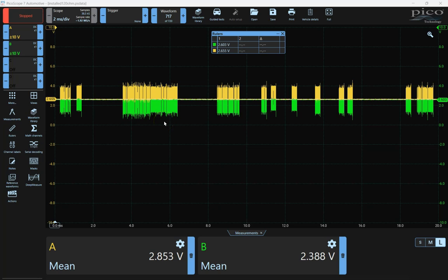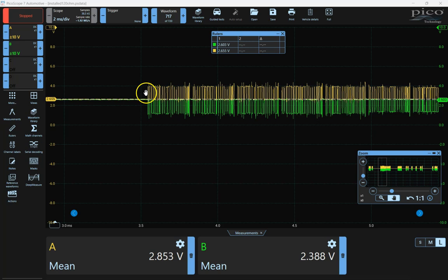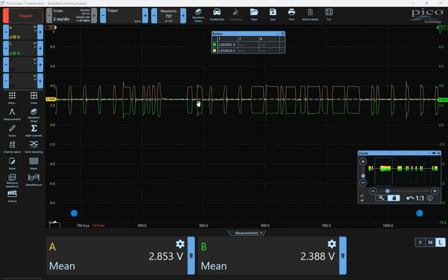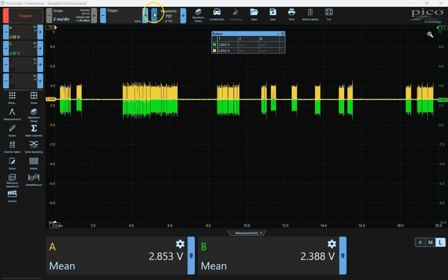This is a machine which originally came with active termination from the manufacturer, and I removed the active terminators completely so the electronics of those devices wouldn't affect the network. And I installed one single 120 ohm resistor. I didn't put one at either end, but you can see this network now seems to be pretty well restored.